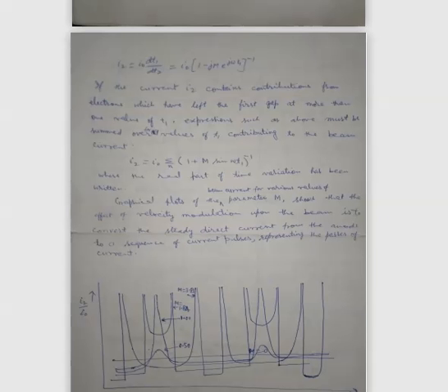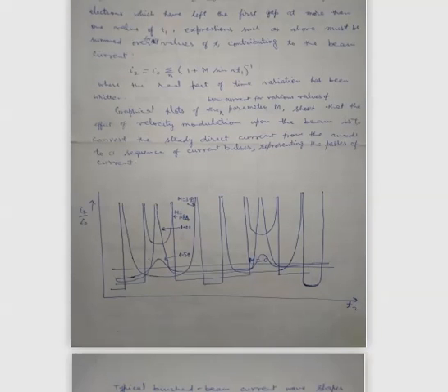So in calculating the current I2, we will also consider the contribution from all the electrons which left the buncher cavity grids at different instances of time t1. So therefore, summing up all these contributions to the current I2, this gives us I2 equal to I0 sigma n, 1 plus m sine omega t1, to the power minus 1, where only the real part in the above equation is retained here.